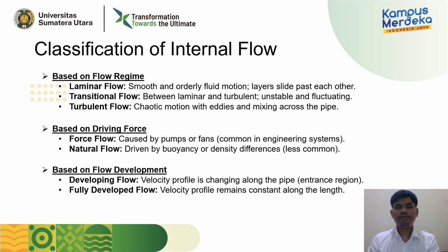The layers slide past each other, which is normally uniform. The second one is transitional flow. It is between laminar and turbulent, unstable and fluctuating, but not as much as turbulent flow. And the last one, turbulent flow, is chaotic motion with eddies and mixing across the pipe.